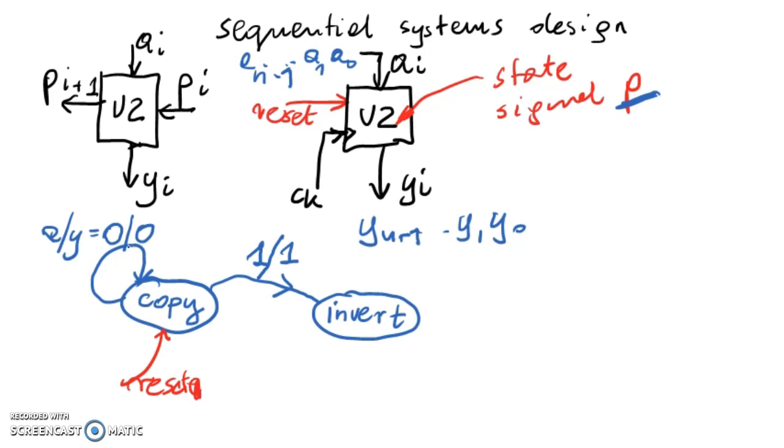That's all about the copy state. You've got the next state defined for A equals 0 and for A equals 1. And after the first one, you must stay until the end of the input number, and invert the bits. So if you've got A equal to 0, you must produce 1. If you've got A equal to 1, you must produce 0. And it is now a fully defined state transition diagram, so we can start designing it.